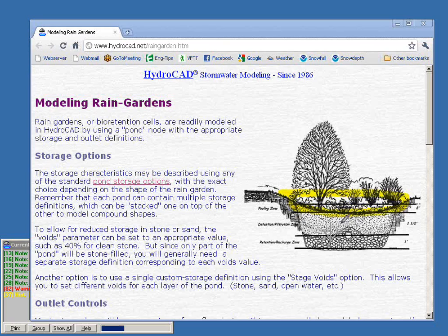So this is to say that the detail of what's going on below grade, although it's critical to you for longer periods of a day or two as the structure dries out, it will have little to no effect on what's happening in the very few hours around your peak flow. So just keep that in mind as you're deciding how you're setting up your model and working out exactly which events you're intending to replicate in HydroCAD and what the objectives are in each case.